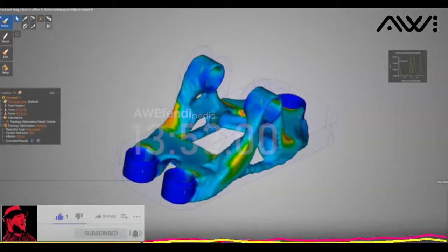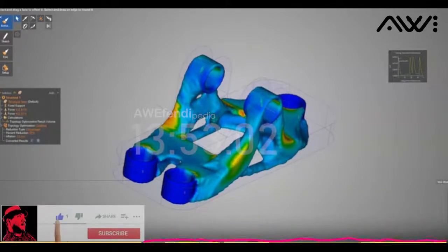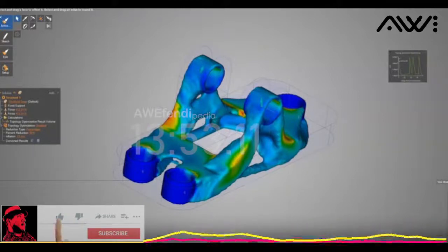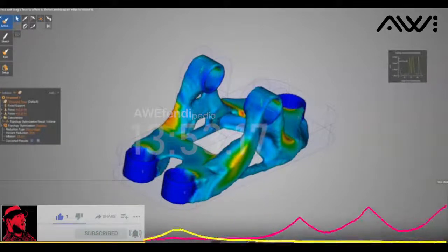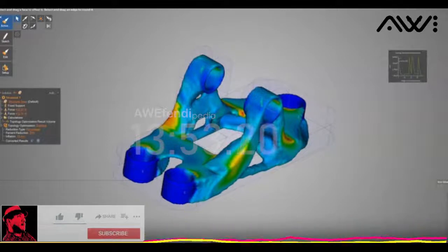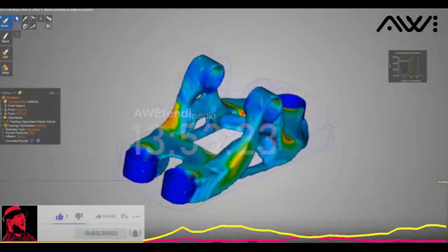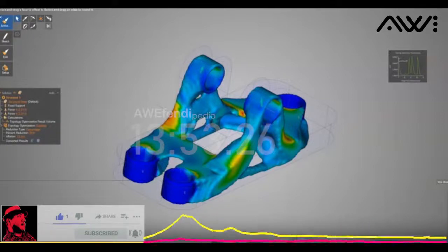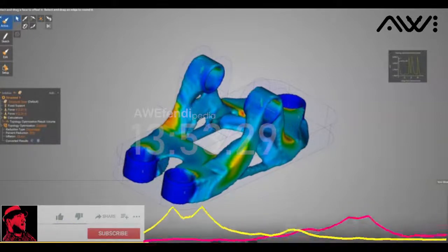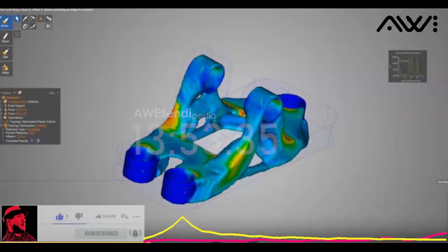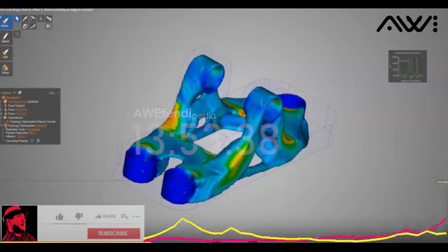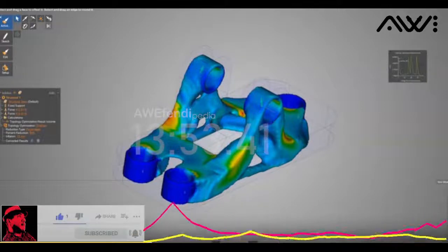Let's say I want to 3D print this, how do I get an STL file? Or I want a CAD-ready model, maybe like a B-rep surface. How do I do that? I'm going to let this iterate a little bit more, and then we're going to kick this off as the STL file. When we talk about STL files, there are 2 ways we can do this. One, if you look at the oatmeal-y looking piece here, I can kick it out just like that. But the cool thing is that we came out with a smoothing function within our software, looking at a deviation and the values here, to get a really clean surface to use as we go to manufacturing.